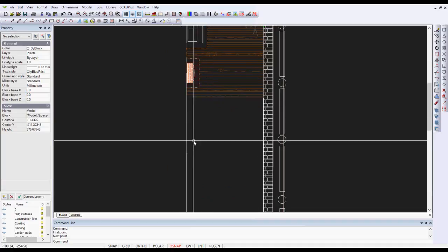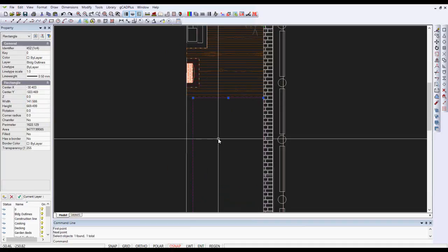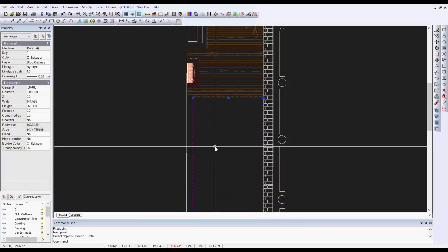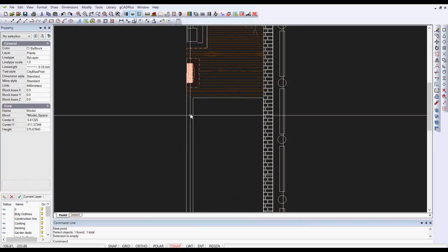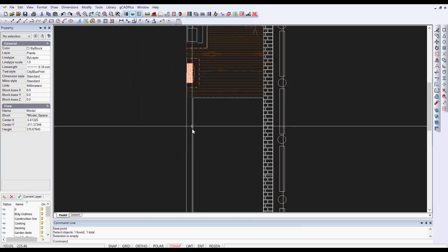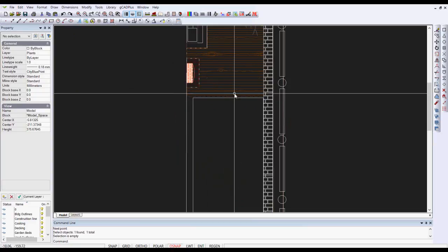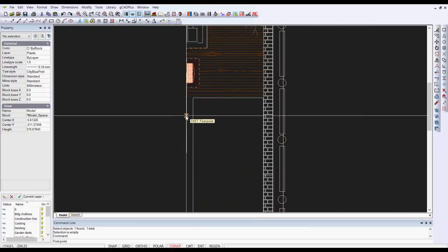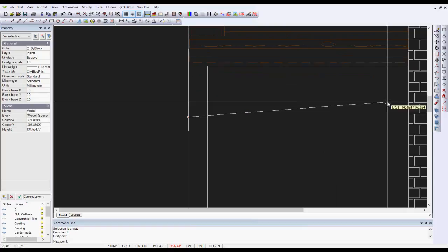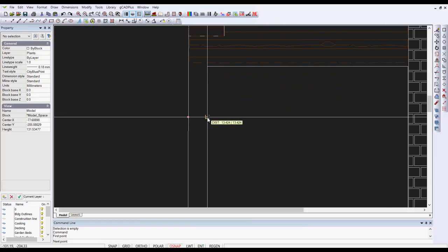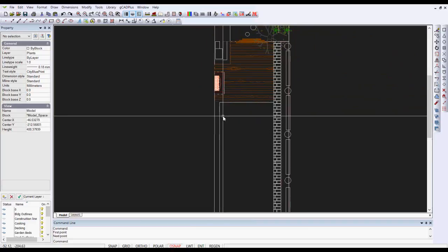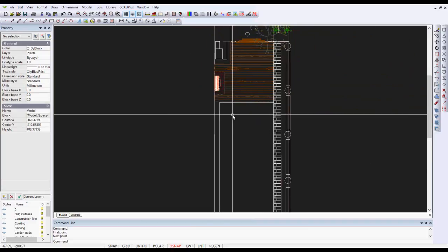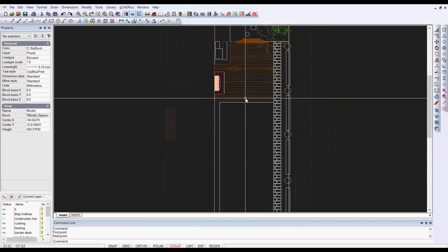Clearly, if this rectangle represents the building outline, and we see a little walkway obviously leading down the side of the house back out to the deck area, and we measure, let's do an accurate measure, and we'll pick near to that point there, and we'll zoom in and we'll say perpendicular to the wall of the building. The unit is 13.42. Now something's obviously wrong here.